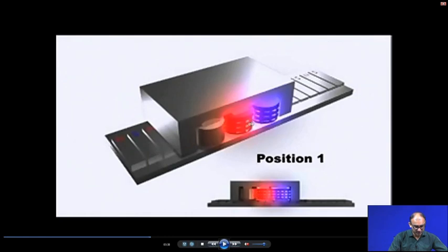So, how does this forcer move? Here, this is position 1. We have 3 coils here, and these 2 coils are energized, and we know that these are the magnets with an alternate pole arrangement: north pole, south pole, like this. So, this is the first position.